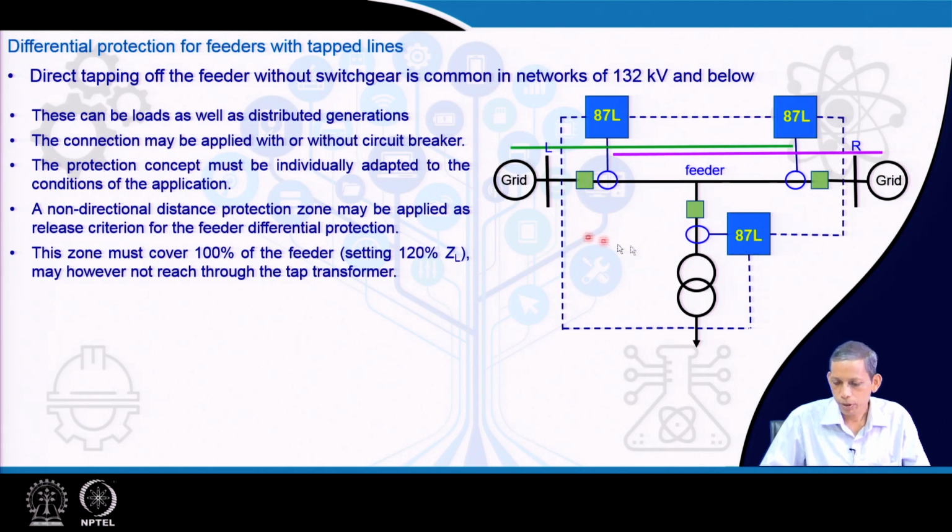Therefore, the differential relay must take that into account. Now, if you have communication information from all these ends, fine, you can use the corresponding KCL, and each relay can decide very efficiently. But sometimes the communication link may not be available, so how to handle that case where there is no provision for a communication link? At times there may also be a failure of communication, so how will the corresponding relay handle that situation?